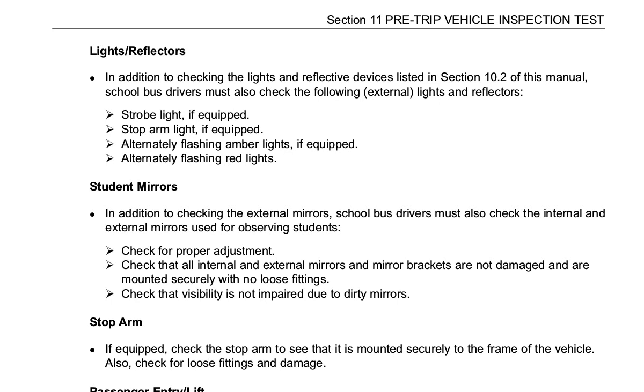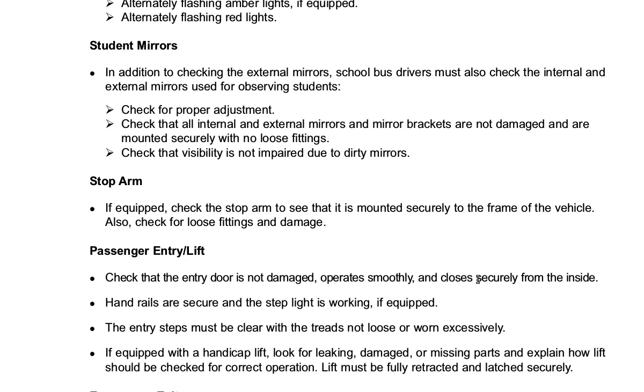Student mirrors. In addition to checking the external mirrors, school bus drivers must also check the internal and external mirrors used for observing students. Check for proper adjustment. Check that all internal and external mirrors and mirror brackets are not damaged and are mounted securely with no loose fittings. Check that visibility is not impaired due to dirty mirrors.